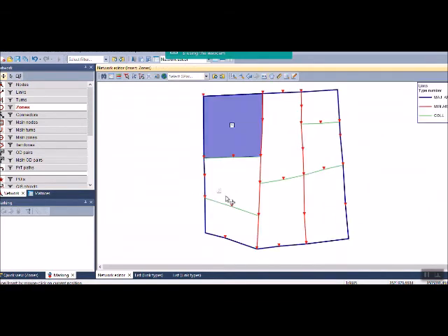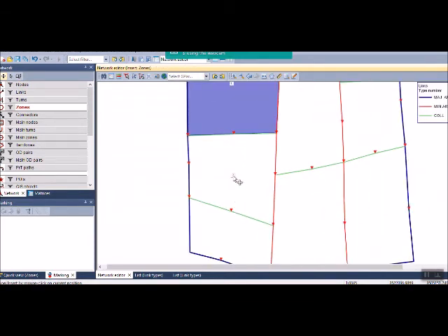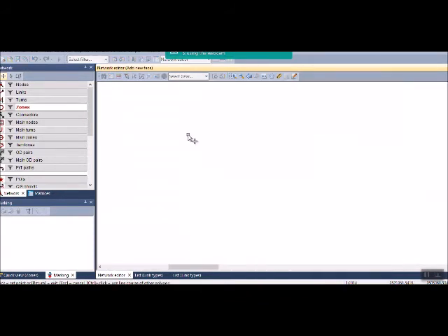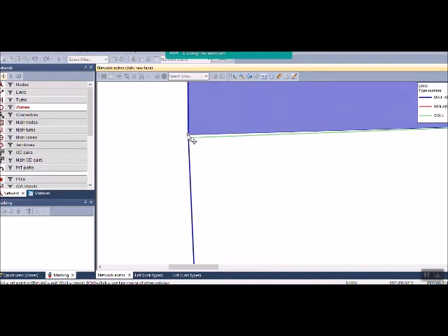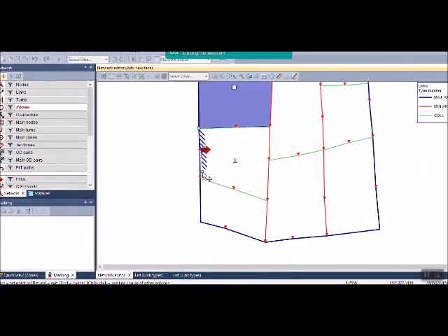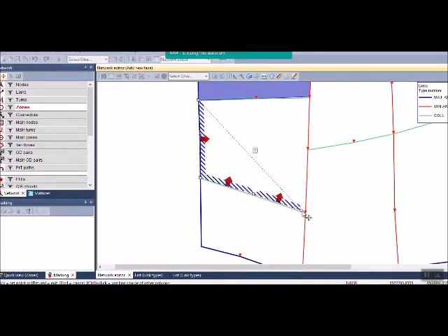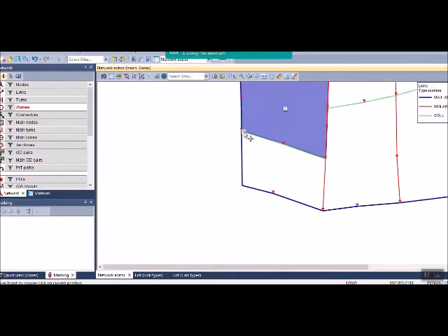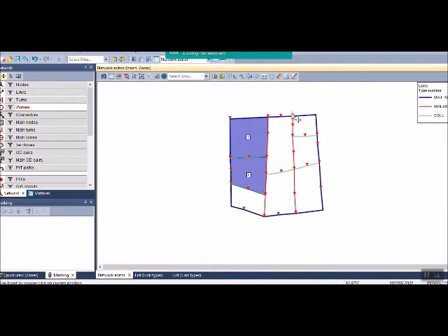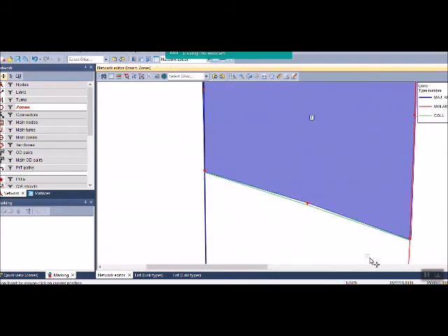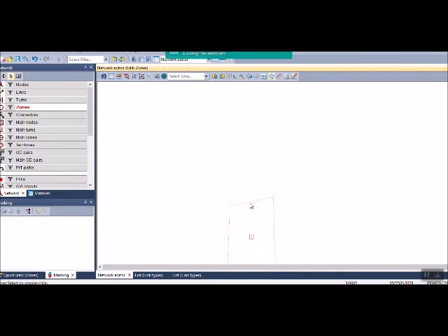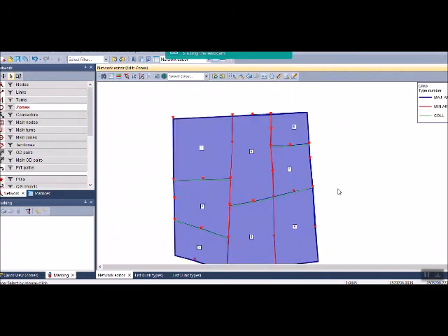We're going to add the second zone, the same thing. This is, for example, the centroid. Zone number two, OK. And you're going to click in here and take care that you click exactly on the end of the adjacent zone, which is zone number one, and like this. Okay, and close your zone. This is zone number two. Zone number three, the same thing is going to be repeated 8 times for the 8 zones we have. Okay, so now I defined the 8 zones I have in my town.